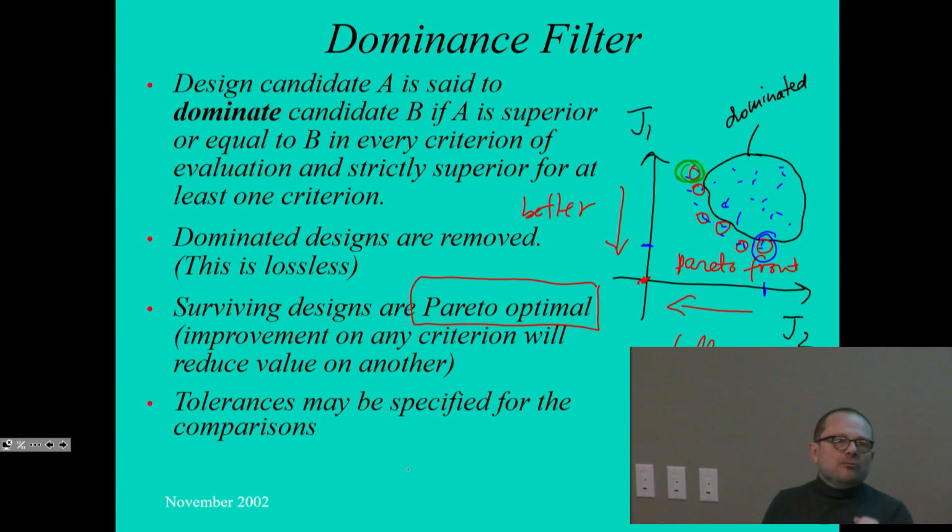Now, when you make comparisons, we're going to specify some tolerances. We're not going to make the mistake that many students make. One of the biggest flaws of MATLAB is that by default it gives you 4 decimal places. So I get answers in homework assignments that look like 179.52735. Do you really think that the last 4 digits mean anything?